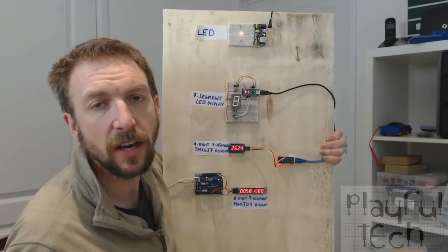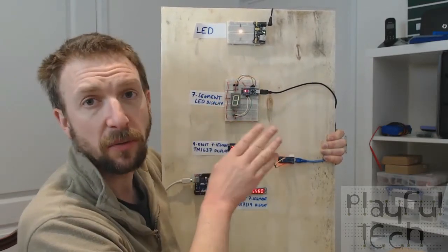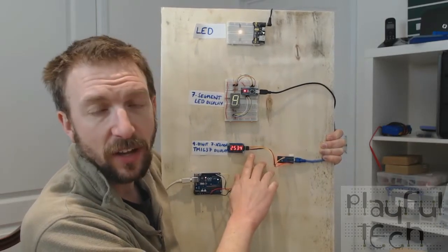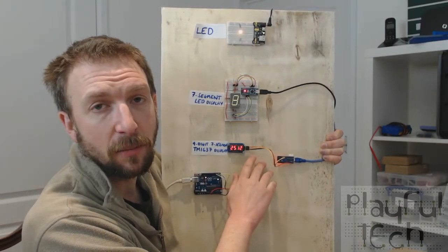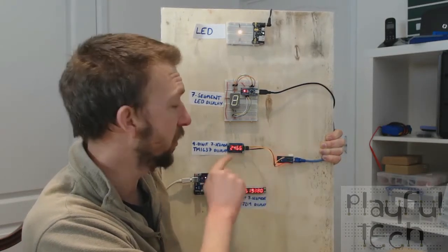And when you're using a TM1637, you don't actually have this mess of wires. It becomes simpler wiring, if anything. You simply have 4 wires. The black and the red cables here are my ground and my 3.3 volt input on this one actually.